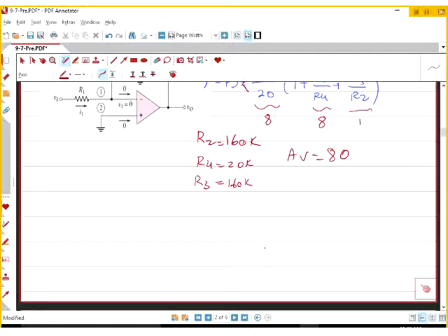For sure, no lower. Higher is a little bit okay. Why? Whenever you design something on paper with the gain of 75, there is no way in the lab you get 75. Probably you're going to get 70 because nothing is ideal. The resistors are not ideal. The op-amp is not ideal. Your gain is going to be lower.